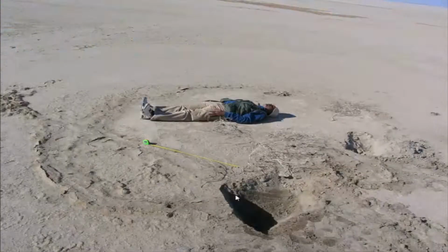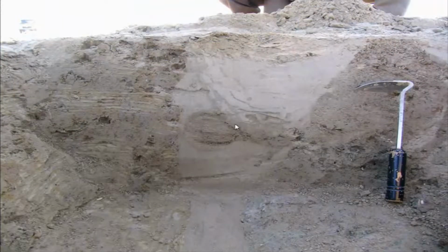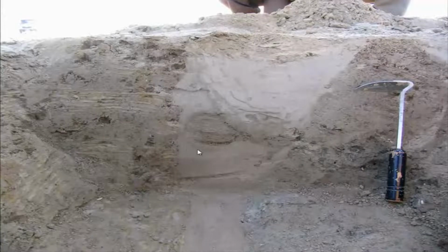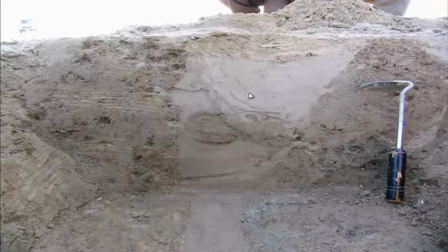For this liquefaction feature, a wide crater, we excavated it, and this is what we found: two conduits which connect from the bottom and resulted in the formation of the sand blow. So here is the close-up of that, and in between what you see here are the clasts, which are the broken clasts of the soil on the way of the sand which traveled through this conduit right up to the surface.